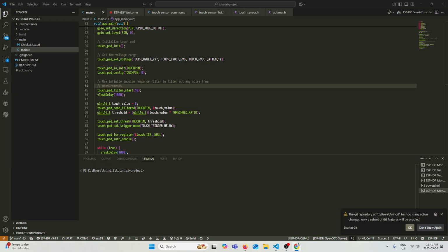The next style of ADC is called a digital ramp or ramp compare. With this style of ADC, a free-running binary counter produces a sawtooth wave fed into a digital to analog converter. The sawtooth signal gets compared to the analog input signal, and when the signals match, the corresponding binary number is output, the ADC's timer resets, and the sawtooth starts over. The sawtooth always starts from 0, so the lower the signal, the faster the signals match, but the higher the signal, the longer it takes. This inconsistency in update frequency can be problematic in certain applications.